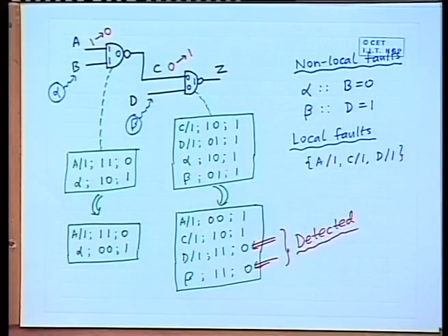So, actually this is a very small example I have illustrated, but this procedure can be applied to much bigger circuits as well. And as you can see, this method is very similar to deductive fault simulation. There also we propagate some fault lists, but in deductive fault simulation we do not simulate the gates when we inject the faults, rather we try to compute the fault list using some set theoretic rules. Okay.